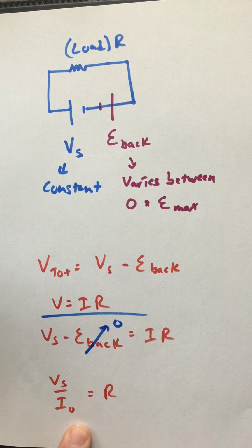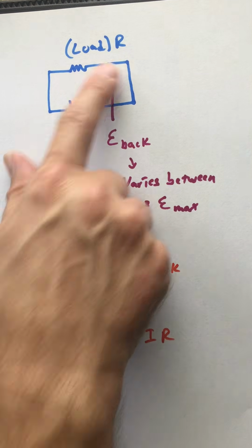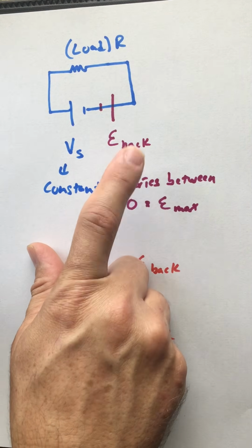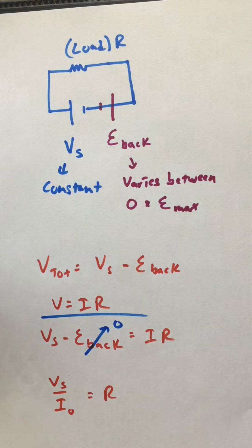Okay, well, what do we do with this? Well, now we know the resistance, and notice the resistance is not a variable. The total EMF is a variable because this component is variable, but the resistance is not. And so then they might say, all right, well, how much current is the thing drawing after it comes up to speed? So I know the resistance now. Let me get a different sheet and solve the next part.